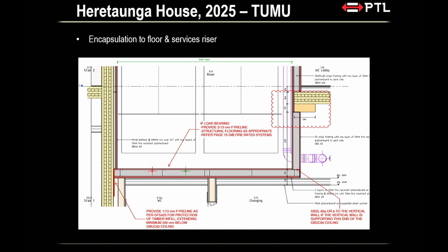Right? Services riser can be quite messy. It's a continuous shaft. So if you have an entire mass timber surface exposed and you're running services, which might be electrical cable, etc., then that's a bit of a risk in there. So batten fix 2-layer of fire line onto that CLT wall.